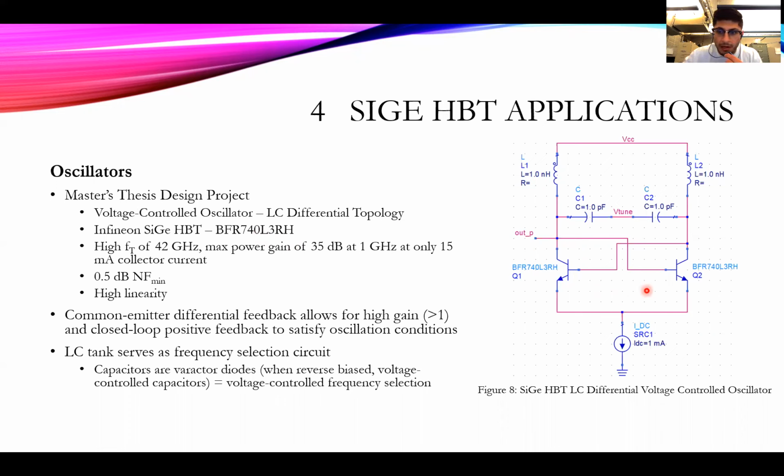So if we think about this in a block diagram, it's essentially just two amplifiers cascaded in series with constant feedback. And since each common emitter is itself inverting, we can achieve 180 degrees here, 180 degrees here. The full closed loop phase is going to be equal to 360 degrees, which is positive feedback, as we know.